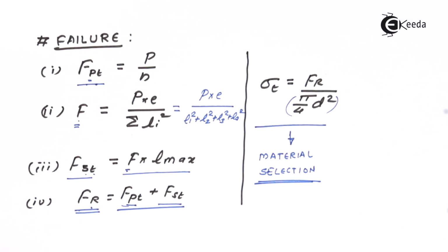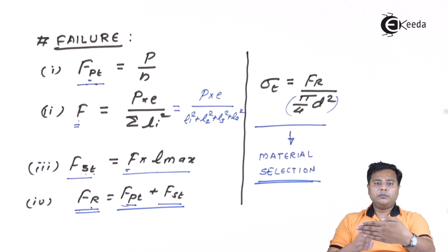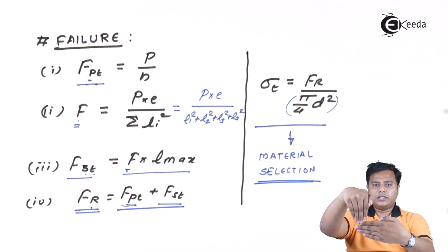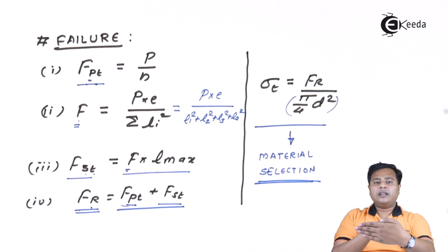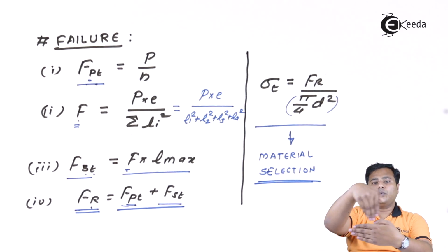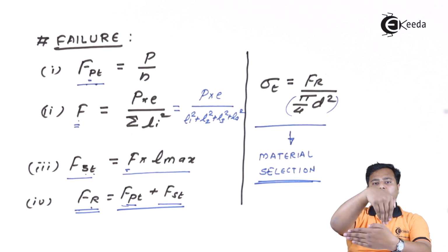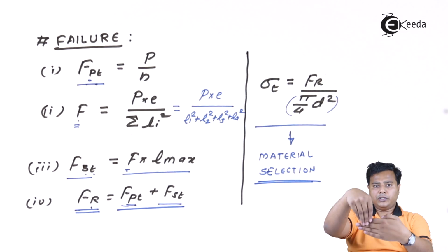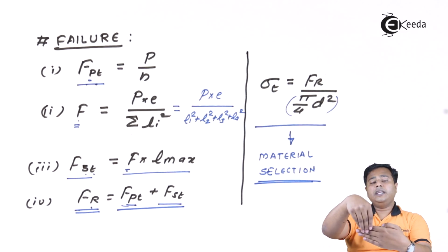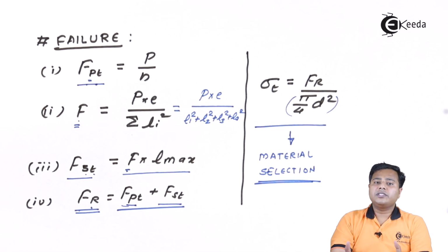Then the second case we have seen where the bolts will be bolted in the same way and the force will be perpendicular. So in the second case, the bolts will be drilled in such manner and the force P will be acting in the same way. The only difference being, in this case, the directions of force P and bolts are completely different. The only thing is the eccentric distance of the wall and force P will be the same. So in such case, there will be direct shear, of course, because of force. Also, there will be the equivalent normal stresses, and because of which failure may occur.